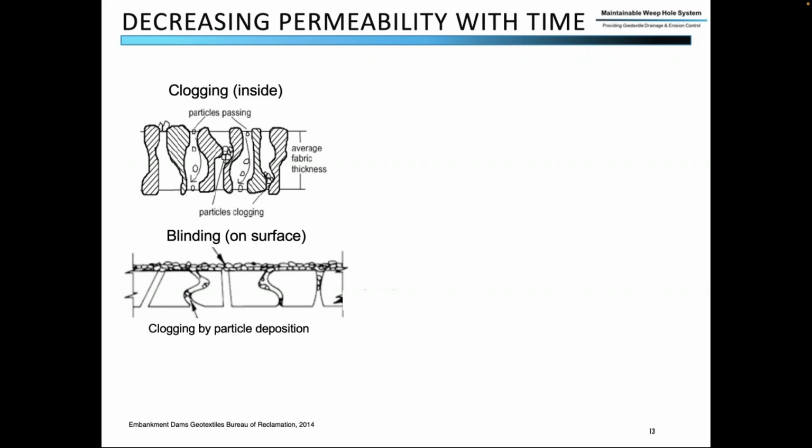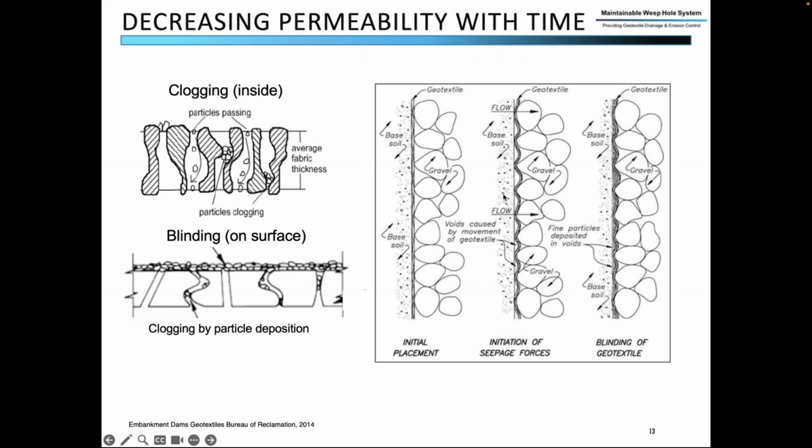If there are any folds or creases or bends in the geotextile filter fabric, those will fill up with very small soil fines, and those soil fines will turn into an impermeable slurry, and that slurry will spread across the geotextile. And that then stops water from passing through the geotextile.